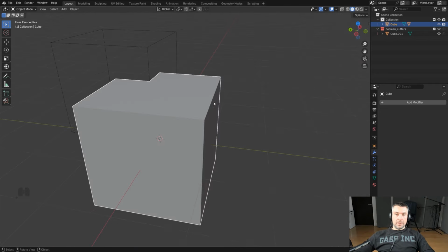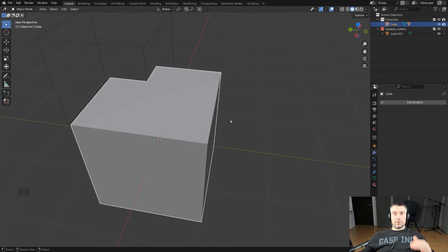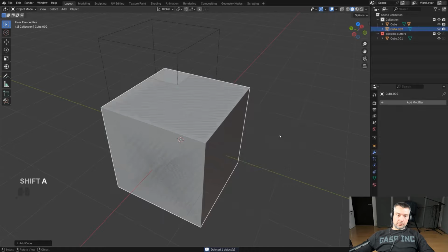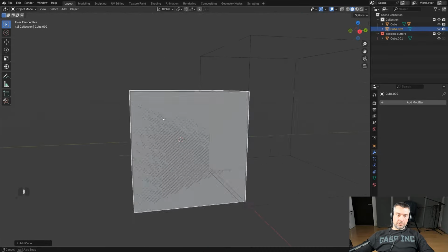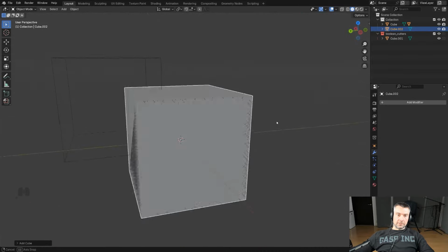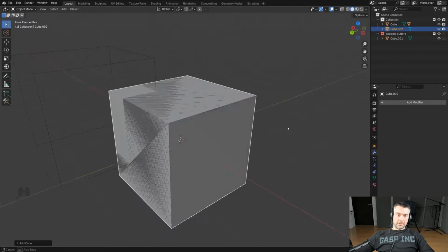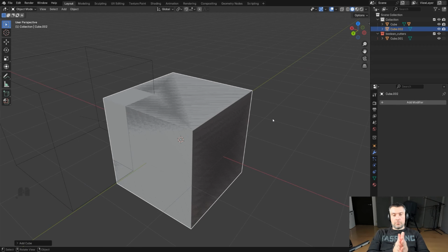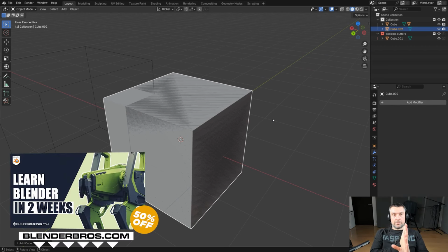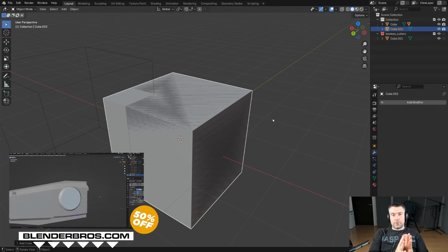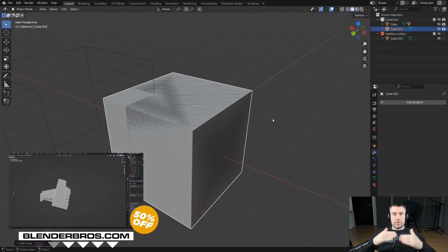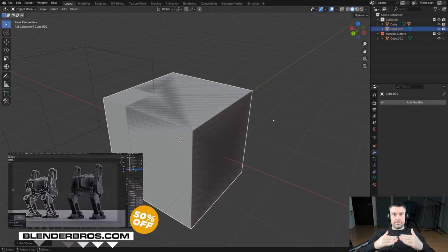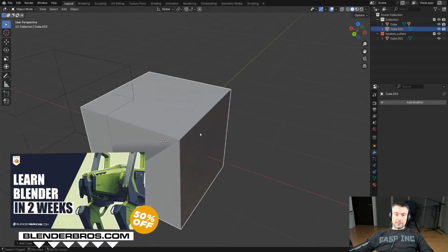Now it's peachy, right? And the last one I'm going to show is booleans, when you cut something on the same level. When I add a cube here, you will see this weird, psychedelic kind of lines going all around the mesh, right? That's called Z-fighting. Z-fighting is basically when you have two surfaces laying in the same space, overlapping, in the 3D viewport. And Blender doesn't know which one is on top, so they kind of fight for the importance. That's why it's called Z-fighting.